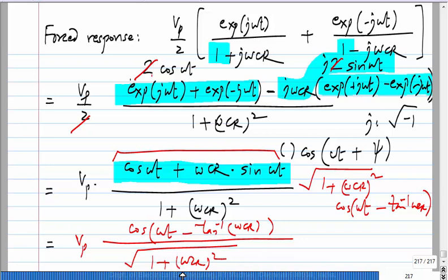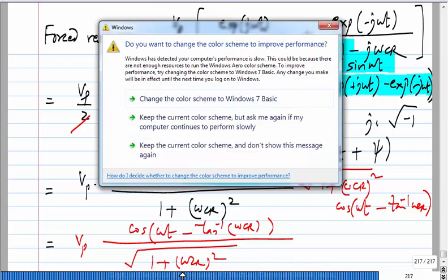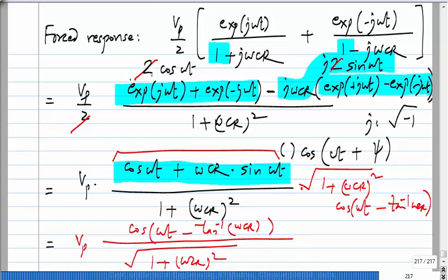Okay. This sinusoid, the real sinusoid, this is not an eigenfunction of the linear system, right? This cannot be expressed as the input was cos omega t. This is not cos omega t times something. Okay. This has some other complications in it. Whereas for the complex exponential, adding a phase is simply like a scaling factor, right? If you have e^(j omega t) and you add some phase, e^(j(omega t plus phi)), that's like a multiplying factor of e^(j phi). Okay. So, an exponential is the eigenfunction of the linear system, sinusoid is not, but the output will be a sinusoid at the same frequency. Were you able to derive this answer or no?